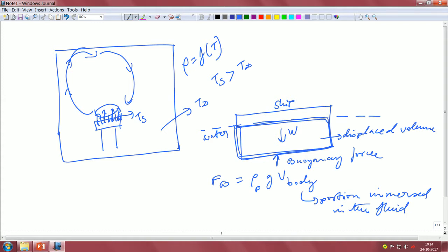On the other hand, okay, the body has got a certain amount of weight, this ship must be having some amount of weight, okay. So, that weight will be nothing but the corresponding solid density, into the V body, into g, right. That is the weight of the body, the weight of that particular section, correct.